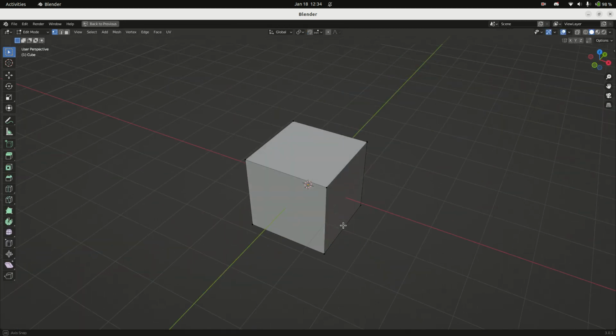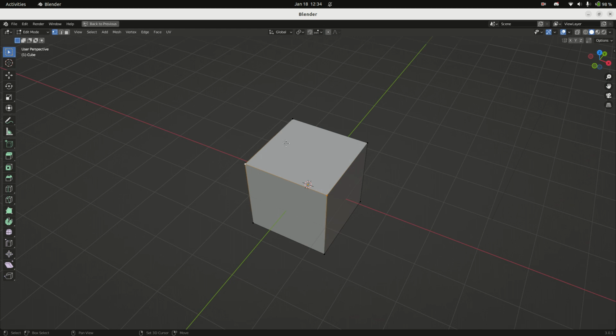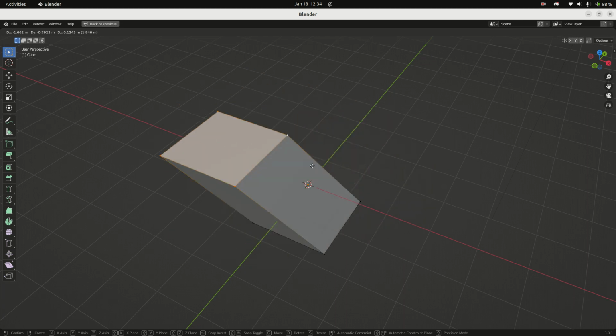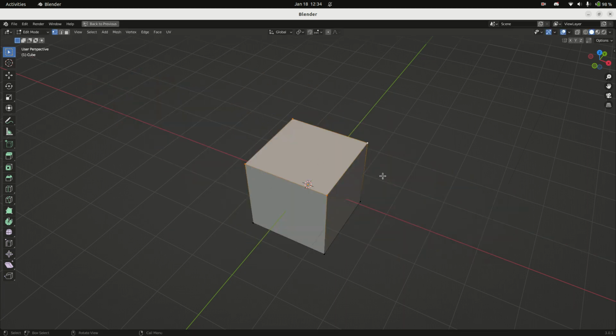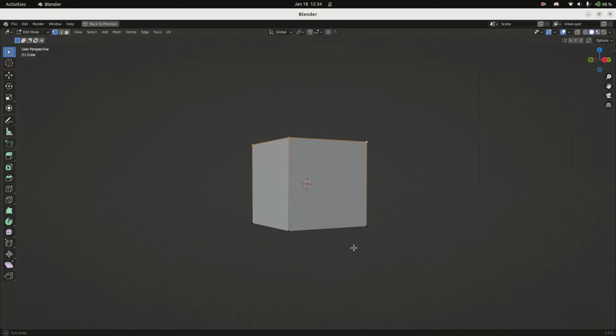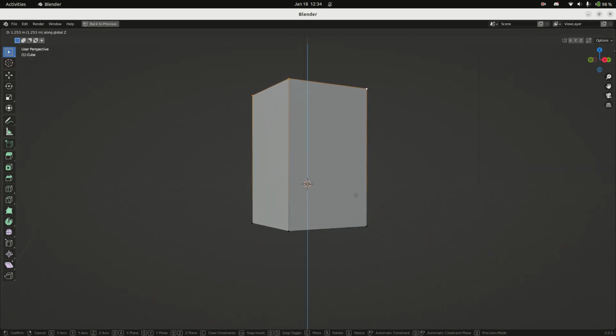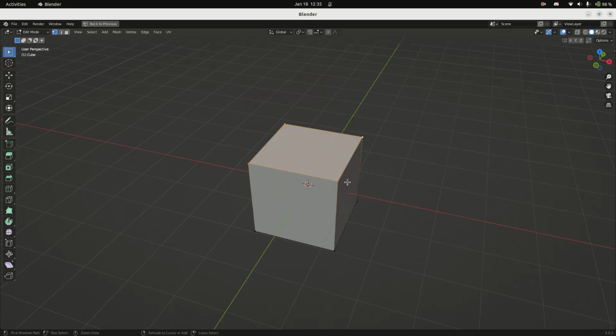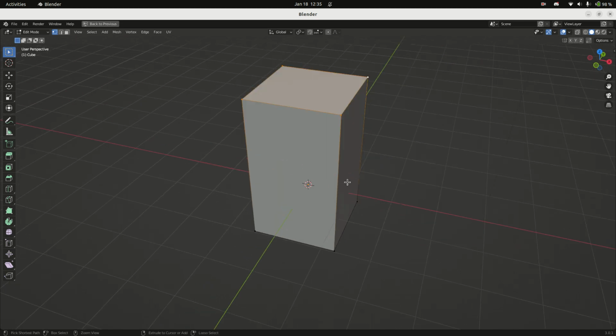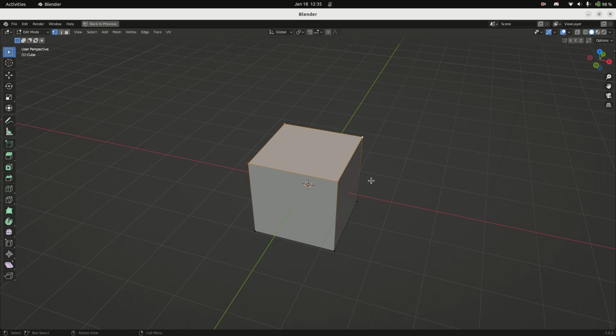All right, now with this selected, I'm going to select some vertices and show you that the commands that I already taught you to grab still apply in different axes. Again, right-click cancels, grab Z, left-click confirms. Control-Z undoes, Control-Shift-Z redoes. Undoes, undoes, undoes.